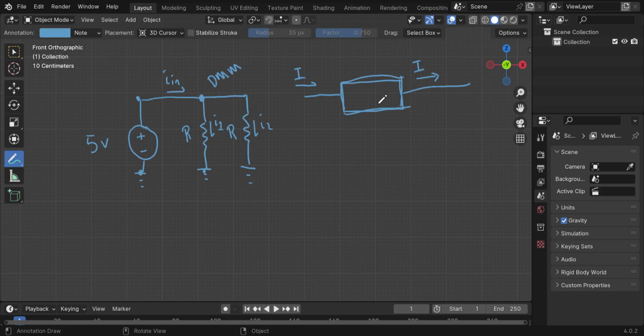None of it will get stored. I mean, you'll have a capacitor maybe that's storing some power, but eventually that capacitor is going to discharge and that current is going to be released. If it gets really hot, some of that energy is going to be released in the form of heat, but on a component level at least, you can think ideally about whatever current goes into the device is the same current that comes out.